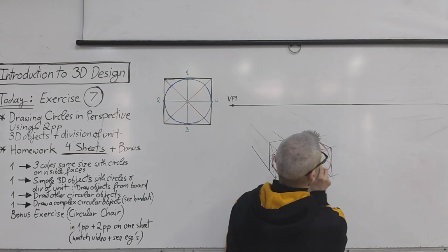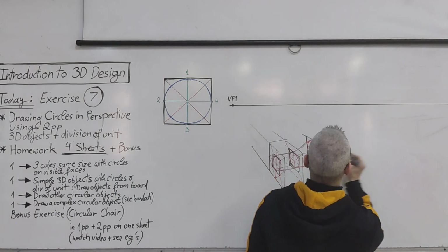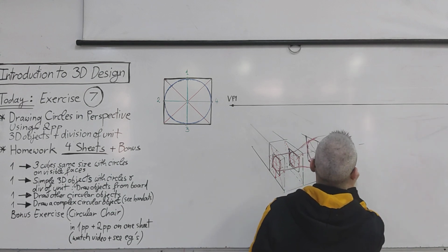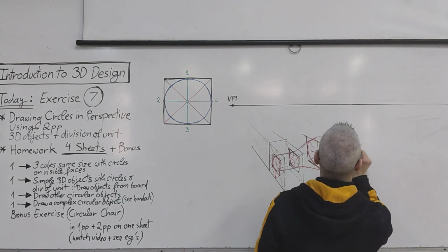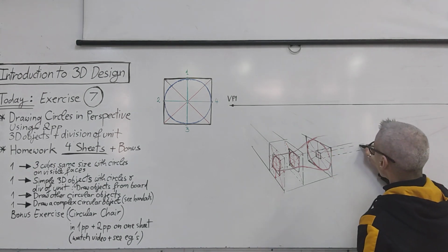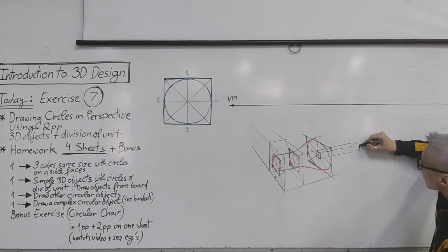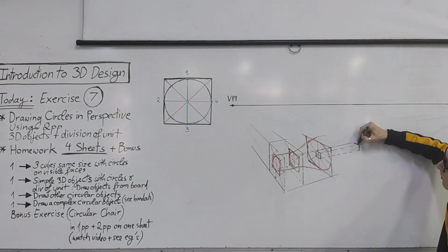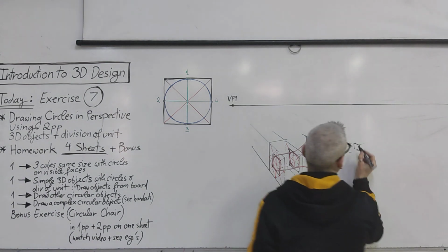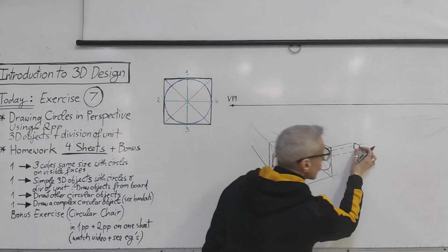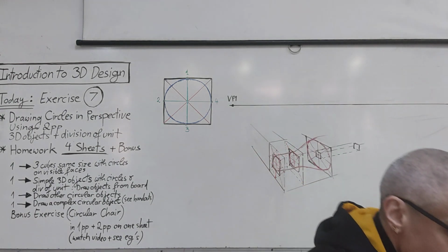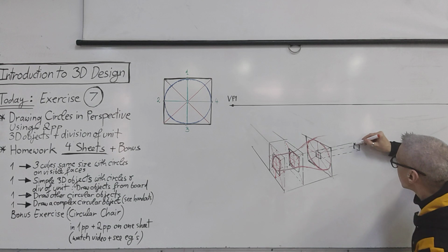Now, this small square, I don't need it here. I need it, for example, somewhere here. So I will take it out. Take it out where? To the vanishing point. And I will draw it wherever I want. Okay, so if I want to draw it here, the same one, this line should go to the vanishing point, until you have the square that you want, located in the location where you want. And then, of course, you need to draw the circle inside here.